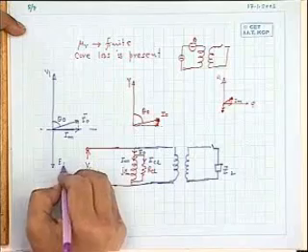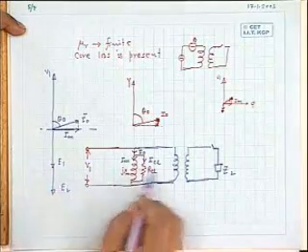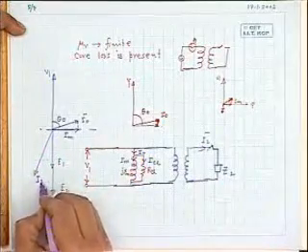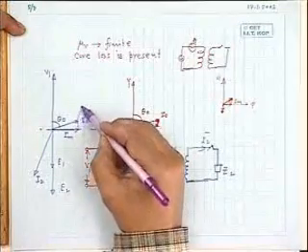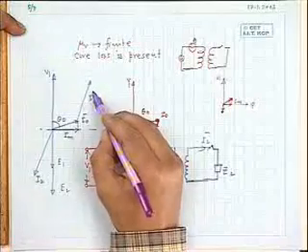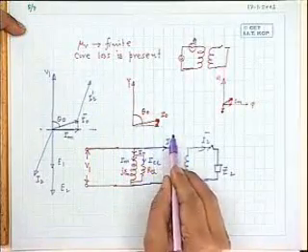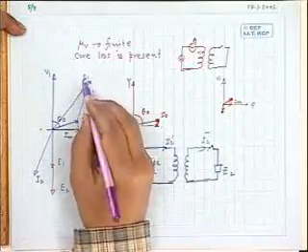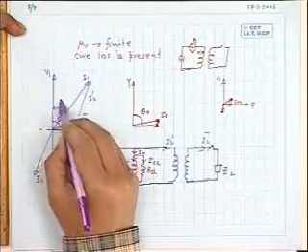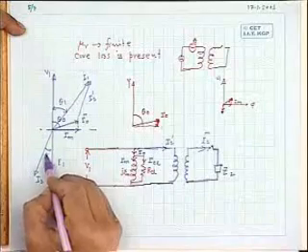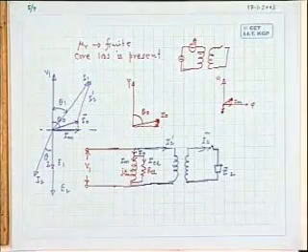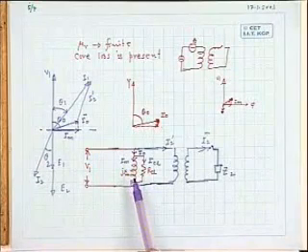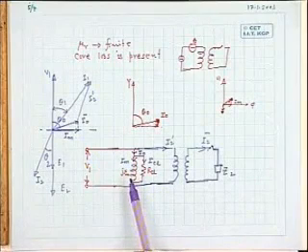In the secondary, now this is the voltage induced, E1, E2, and your secondary current, if any, because of loading, will be some I2. Then this I2 will have a reflected component here. You add to I2 this I2 dashed. Then you invoke all the conditions of the ideal transformer that we have studied, and this will be your total primary current I1, and this is your primary power factor angle theta 1, and this is your theta 2. Therefore, core loss and the magnetizing component of the current can be taken in this fashion.